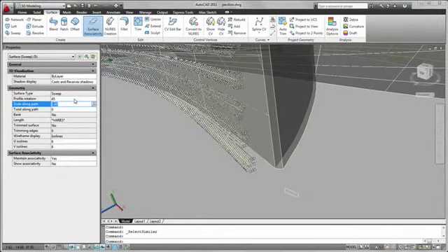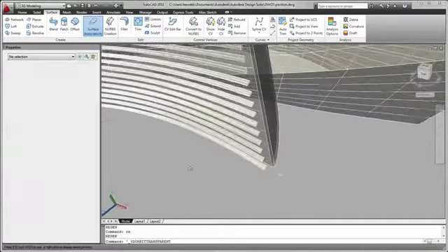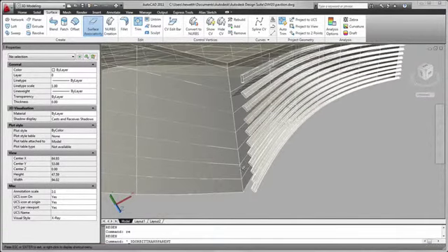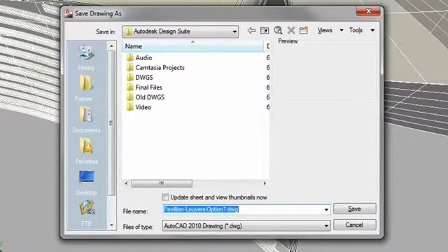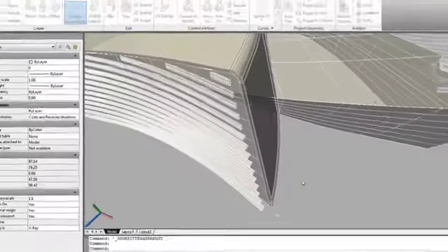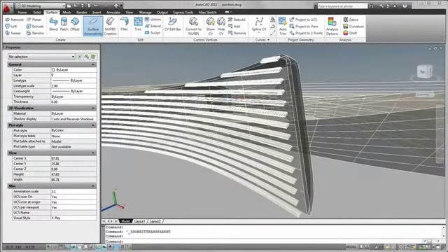At this point, I have a concept for solar protection, but the only way to validate and adjust this design to meet my intention is to send this data to 3ds Max Design 2011, where I can perform an accurate daylight analysis and measure the light intensity.